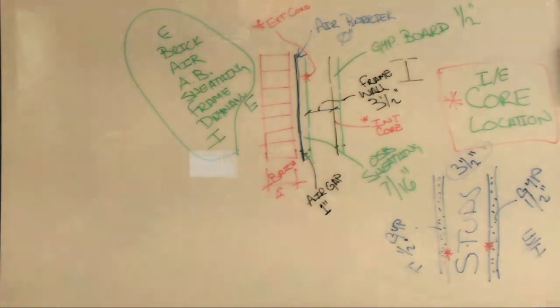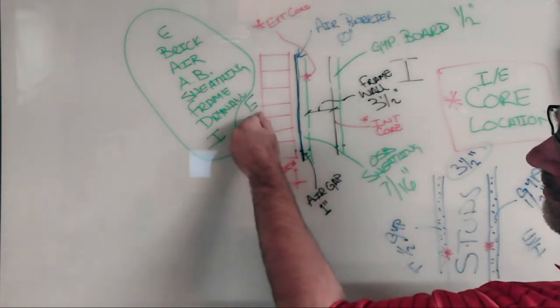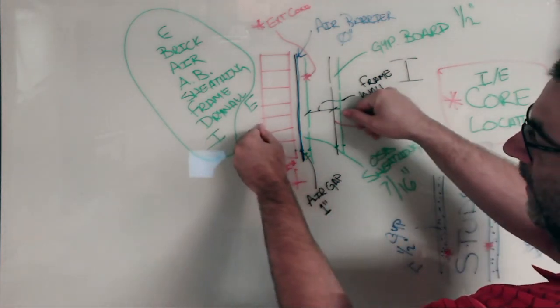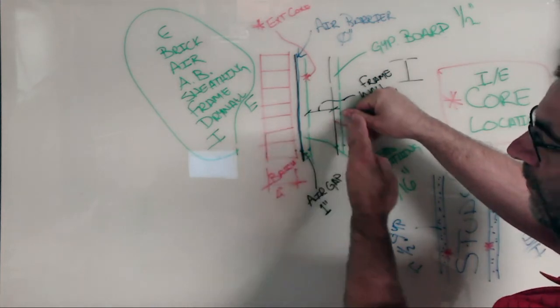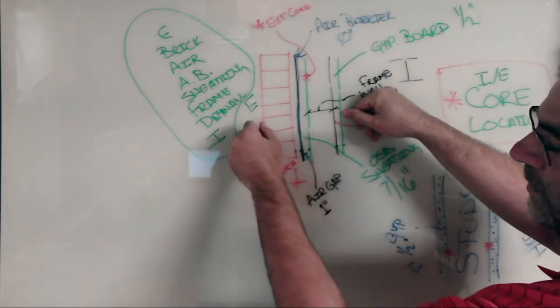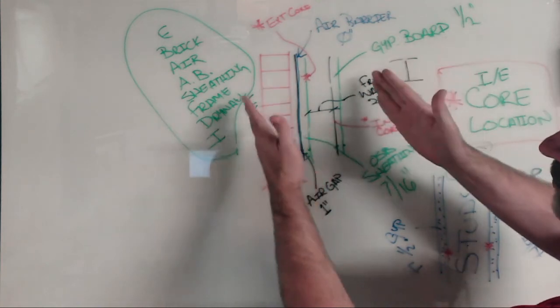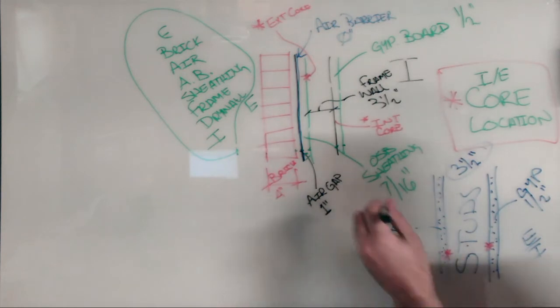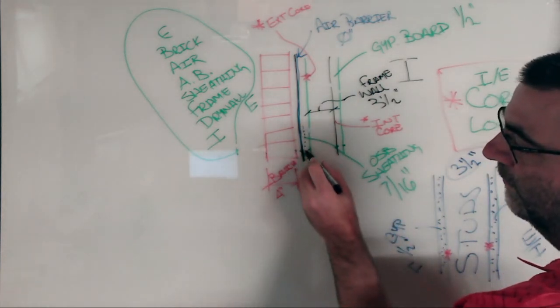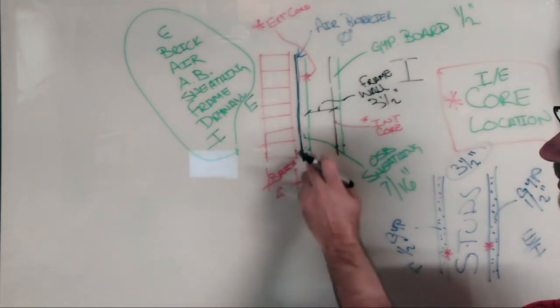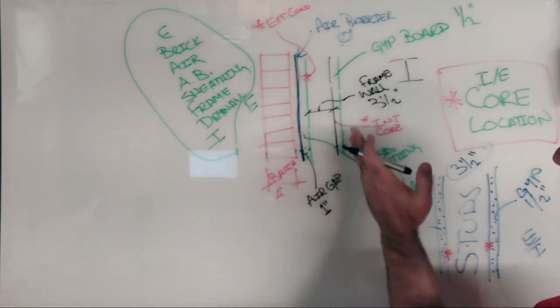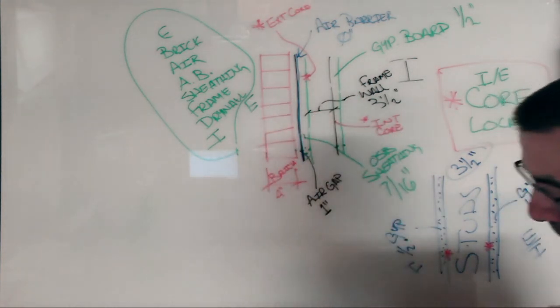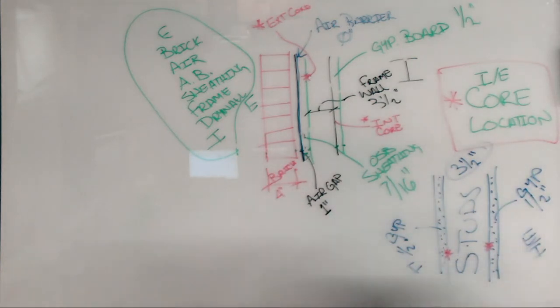Okay, so we have wall center line. What Revit is identifying as a wall, it's identifying from the out of the out to the in of the in. It doesn't really care about what's what. It's just saying from here to here, how big is it? It's 12 inches. Well, the center line's at 6 inches. And that might fall right here in the middle of the area. Revit doesn't care. It's literally going, what's the exterior face? What's the interior face? Get me the dead center. That is wall center line.